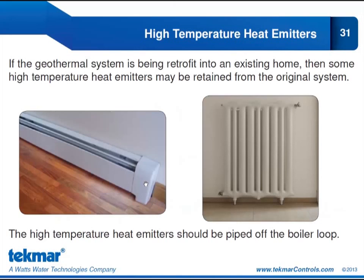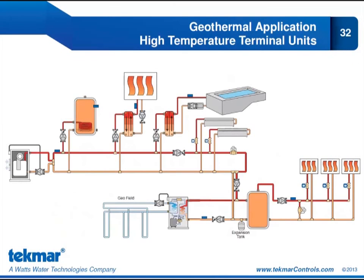Now the question is, how do we account for those? Well, in this case, we want to make sure they're piped off the boiler loop. And the reason we want to do that is because we don't want to drive our buffer tank target temperature too high. Otherwise, we're going to see that heat pump get locked out. And we want to avoid that. So make sure if you do have high temperature terminal units that they are piped off the boiler loop. We want to keep them off the tank loop.